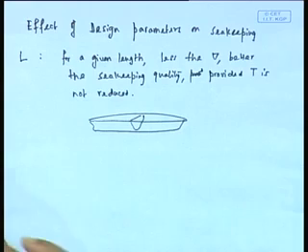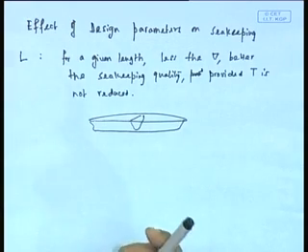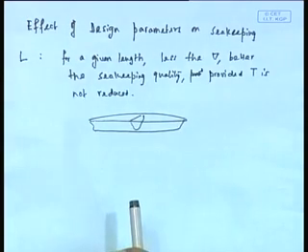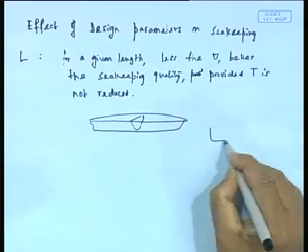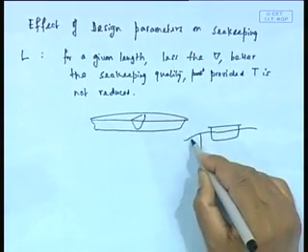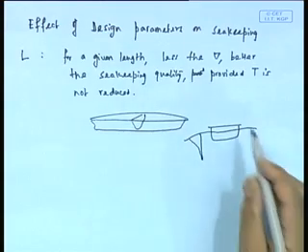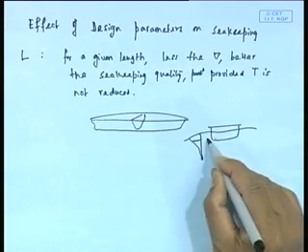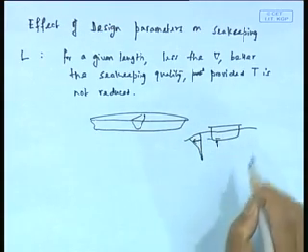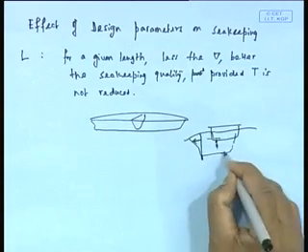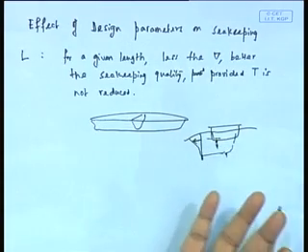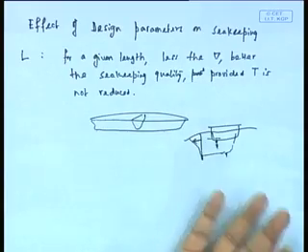It's also obvious, you can just think intuitively. If you have a shallow draft vessel, now consider wave effects and wave forces. If you look at this vessel, the wave goes like that. The wave effects go like a parabola. Now, if the load that comes at this level is of this magnitude, but if you have a deeper vessel, you will have a much smaller one. So the exciting force that tries to push it up and down, causing pitch and heave, is going to be less.